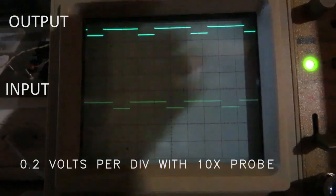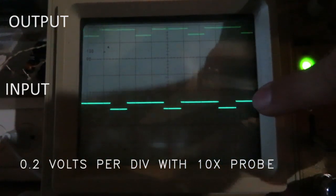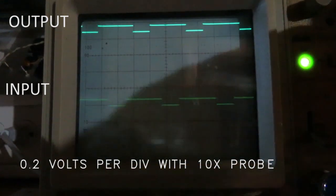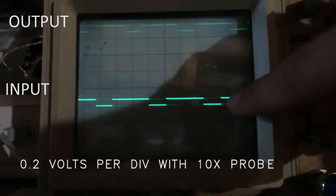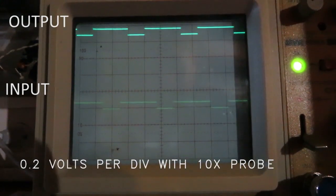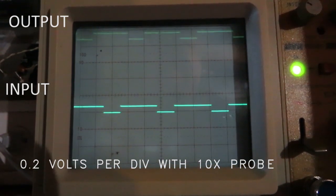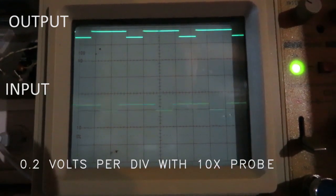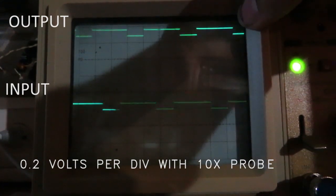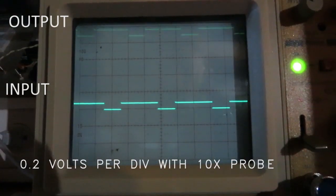Alright, so now you can see the top one here is channel 2, the bottom one here is channel 1, and channel 1's input signal is about, let's see, it's 1 division and about a quarter division there. So that is about 2.25 volts, and up here we have, let's see, that's one division and almost 2 divisions, so that'd be almost 4 volts there. So about 3 and a bit volts.